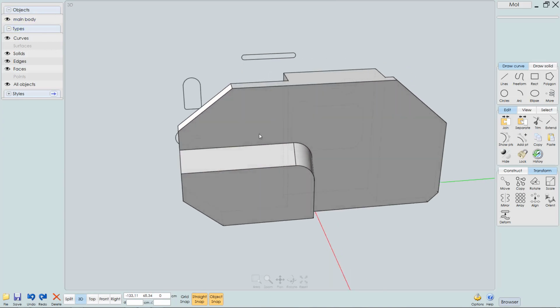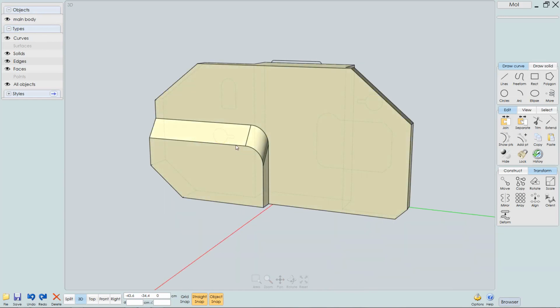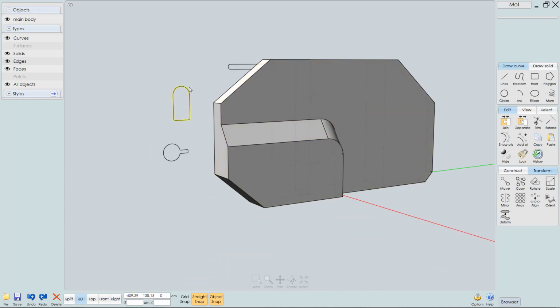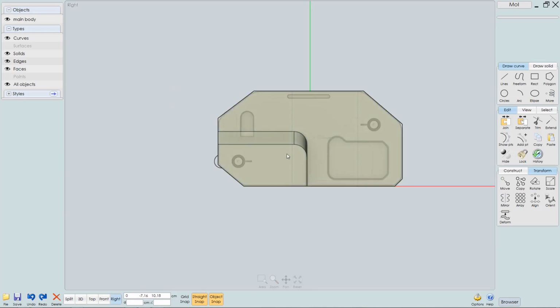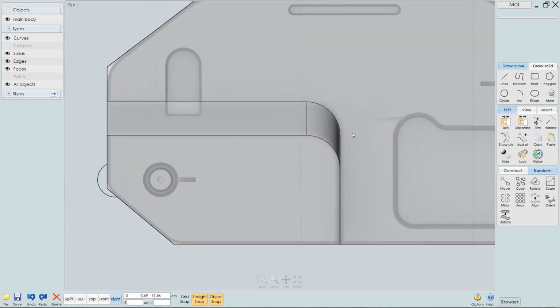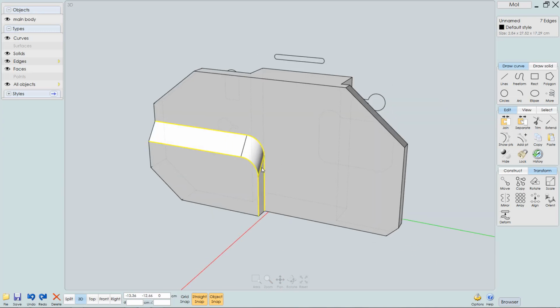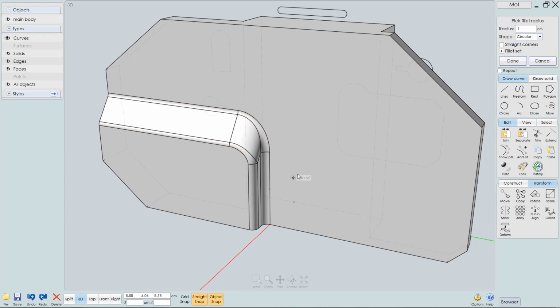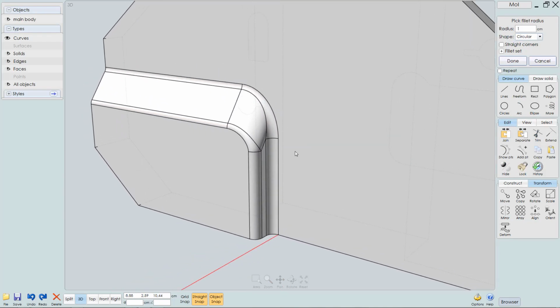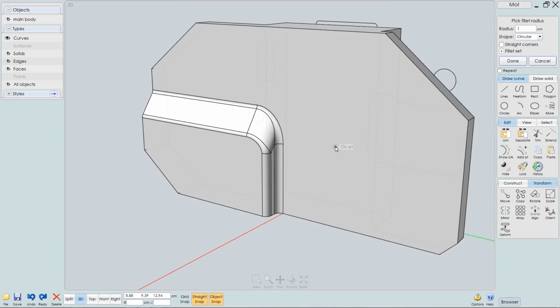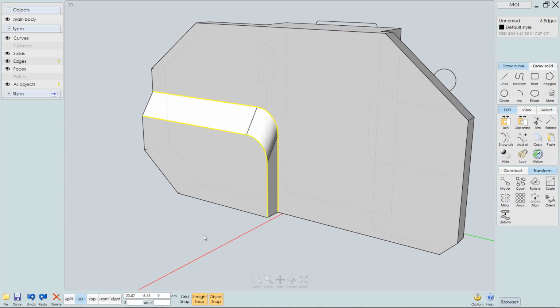Switch to the perspective view, and before I continue, I want to add the fillets on these edges here. And one of the reasons is because it will make it easier later to use Boolean operation to get that shape into this part of the object. And you can see in the reference image that we have these rounded corners here. So let's select the object and let's select these edges. And I'm going to fillet them. And you can see the fillet looks a little bit uneven. And also, I think I'm going to apply 2 different fillets to these edges. So I'll just hit Escape and